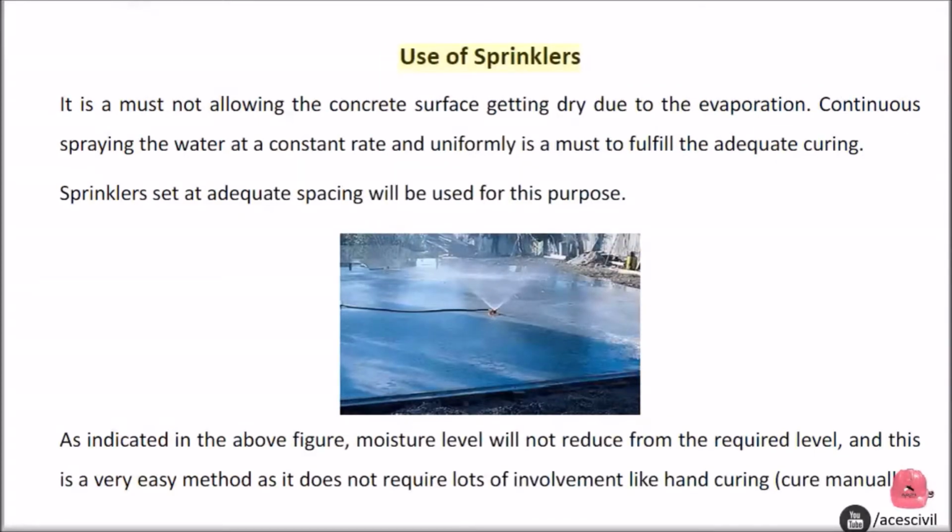Use of sprinklers. It is a must not to allow the concrete surface to get dry due to evaporation. Continuously spraying the water at a constant rate and uniformly is a must to fulfill adequate curing.